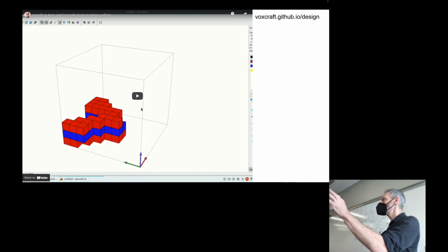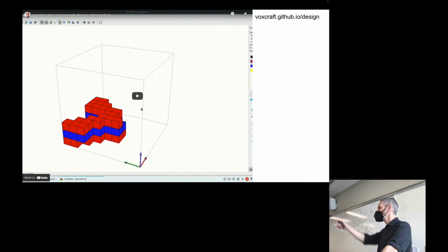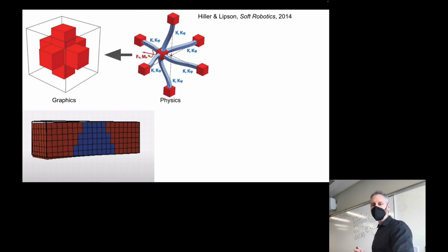You're right, they're modifying some of the coefficients, some of the parameters that describe that beam. Which ones? It is expanding and contracting, but how? Remember, the beams are like a fancy version of a spring. We actually saw some experiments where people were combining motors and springs together. Just like changing the spring constant. Changing the spring constant, right? The resting length. So in simulation land, this is a little bit unrealistic, right? But the motor is somehow changing the rest length of the beam. The beam is going to try and relax back to a longer beam, or a twisted beam, or a sheared beam.